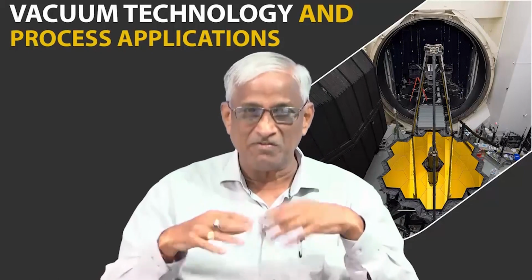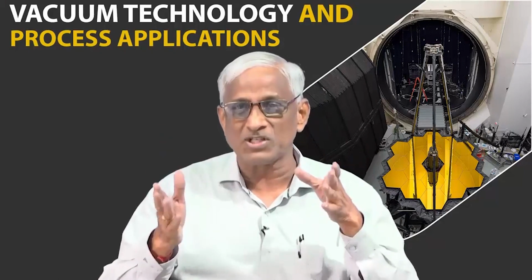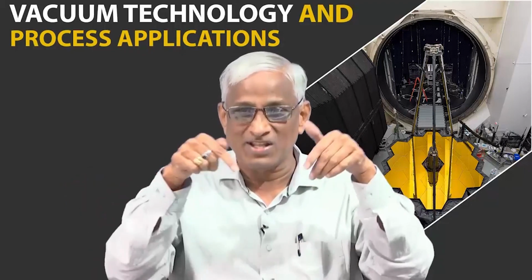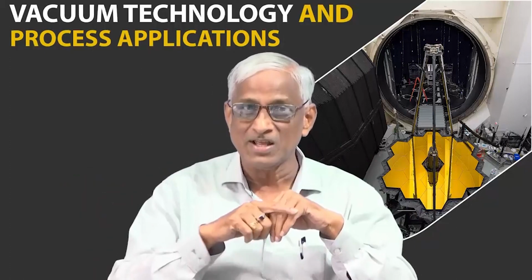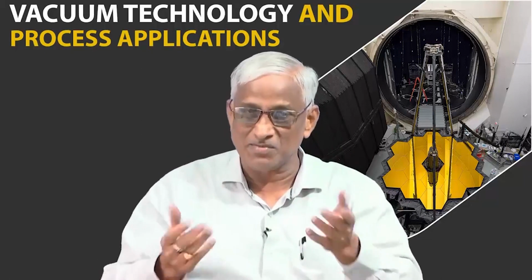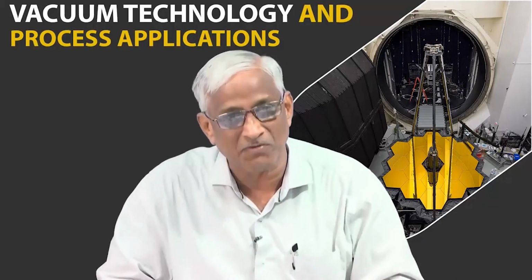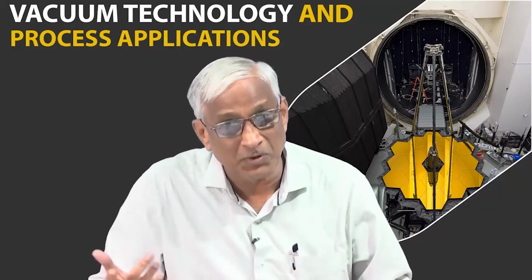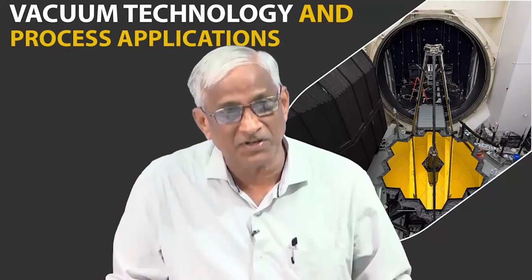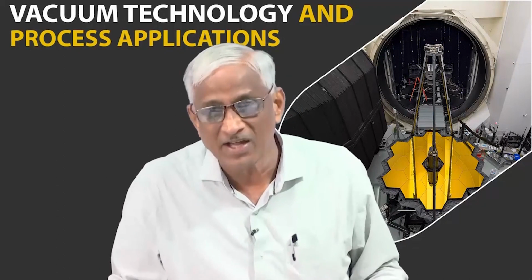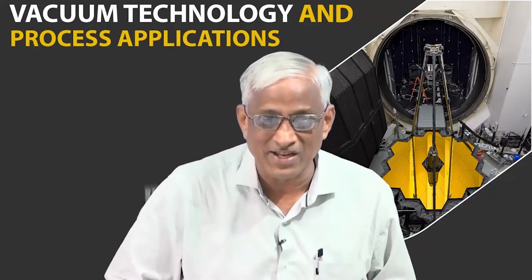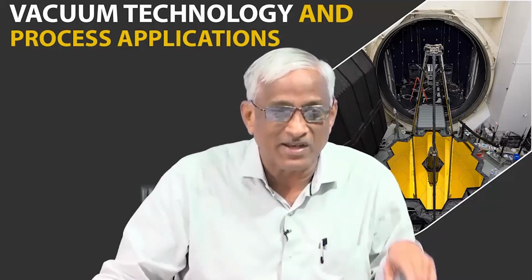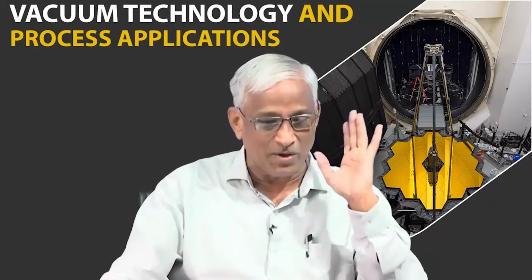But there are lots of ways to overcome this. There is a lot of research going on in aluminum welding, but aluminum is a highly conducting material. Thermal energy concentration is not possible on one side, the melting point is small, and oxidation is a big problem. So, all these three challenges are being worked out by metallurgists and mechanical engineers for good aluminum welding. As and when it comes out, because of its light weight, it is going to dominate stainless steel, because in vacuum aluminum degassing is smaller. But right now stainless steel is still the dominant material.